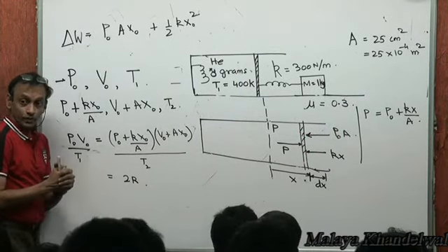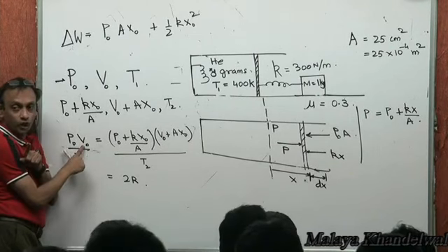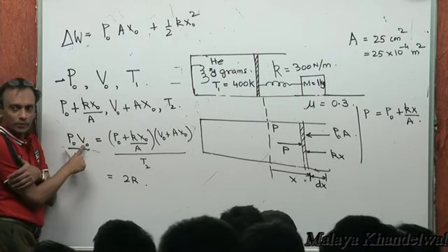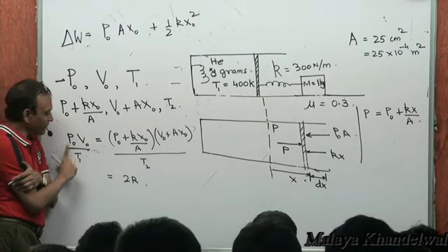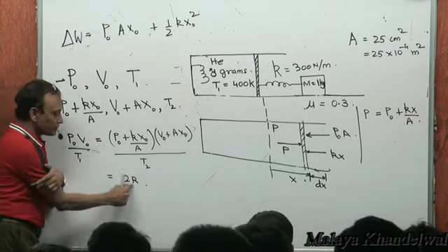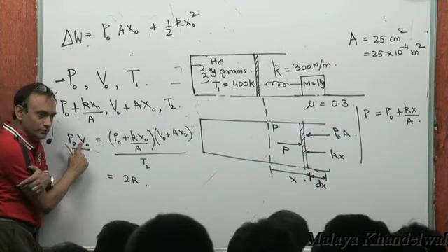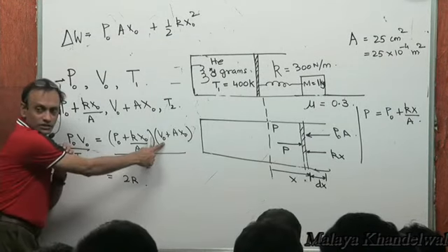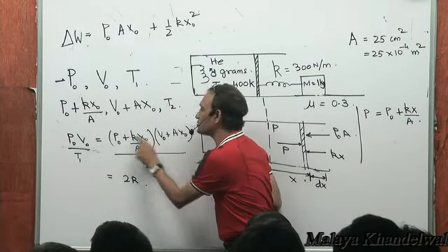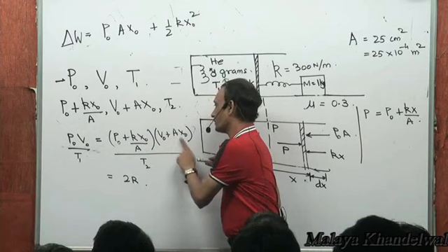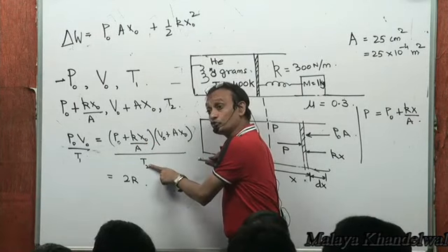Now very clearly, this gives me an opportunity to calculate V0, because P0 is known, 1 atmosphere, 10 to the power 5. T1 is 400 Kelvin. This right hand side is known to me, so I know V0, which I can plug into this. X0 is known to me, P0 is known to me, right? So I can calculate T2 from these considerations.